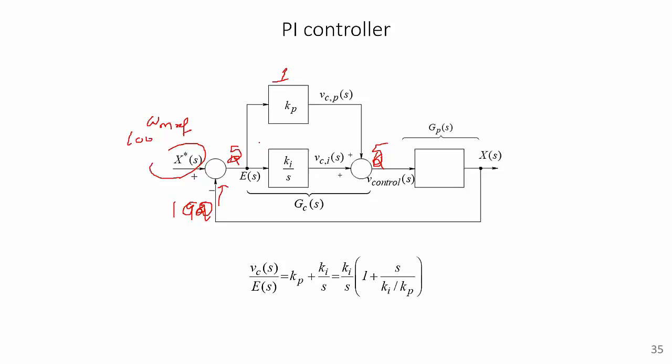The problem with just using a P controller is that as soon as the speed reaches 100, the error becomes 0, which means the applied terminal voltage would end up being 0. If there is any frictional component, which there would be in any real world application, or any load torque on the rotor shaft, the motor would start decelerating because there's no longer voltage applied on the terminals. So the speed can never be maintained at the desired 100 if you're using only a Kp controller.